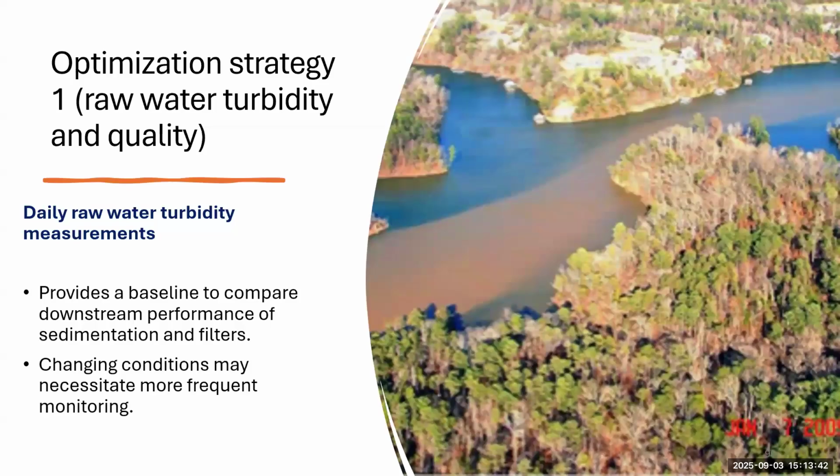And there are some optimization strategies I want to talk about. The first one starts with daily water quality measurements of our raw water. First of all, we would want to measure, for example, our raw water turbidity, and that would give us a baseline to compare our removal rates to, but it will also let us know what the changing conditions are that we need to prepare to react to.